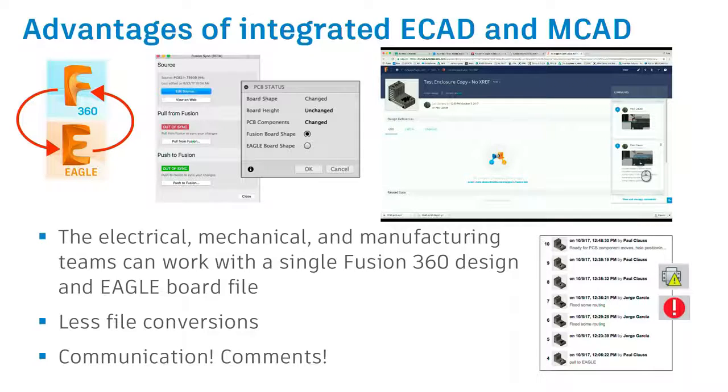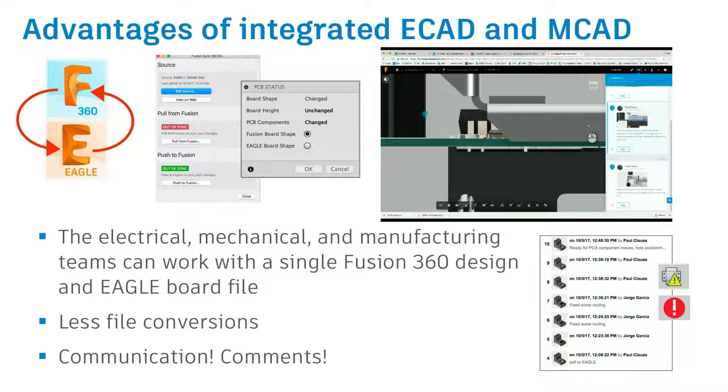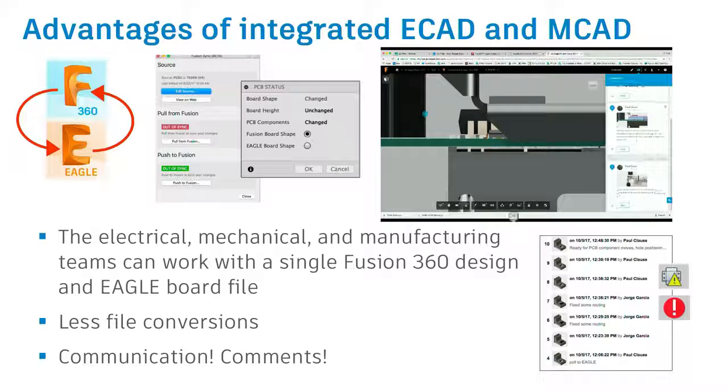And that actually shows an example with the Z height. From looking at the board and our sheet metal cap, I realized that this circuit component sits a little higher than we need it to. How can we work around it? Yeah, exactly. So you'll get the violation from the height, so he either has to fix the enclosure to accommodate this.